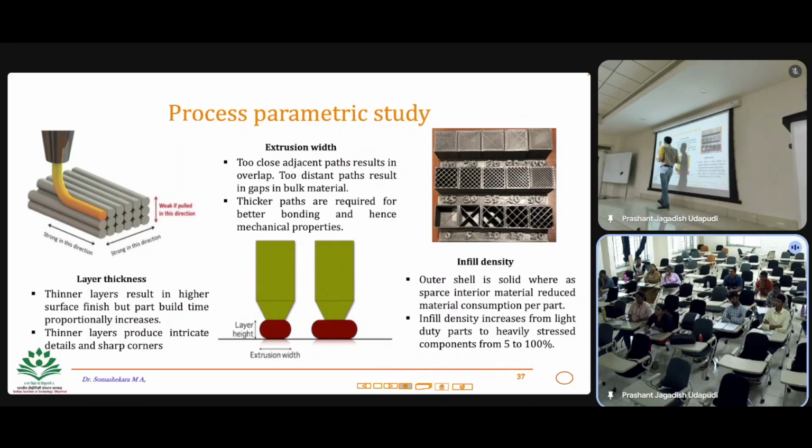But what are the properties when you compare x and y versus the z direction? Are they uniform in terms of properties, right? Or what is the variation when you compare x and y and z direction? And also when you print, what kind of infill pattern? Nowadays, a lot of people are exploring how to reduce the material. Many times we don't need solid structures when it comes to the component and its functionality, right? So can you save the material by adding the material only selectively, or use different infill patterns?